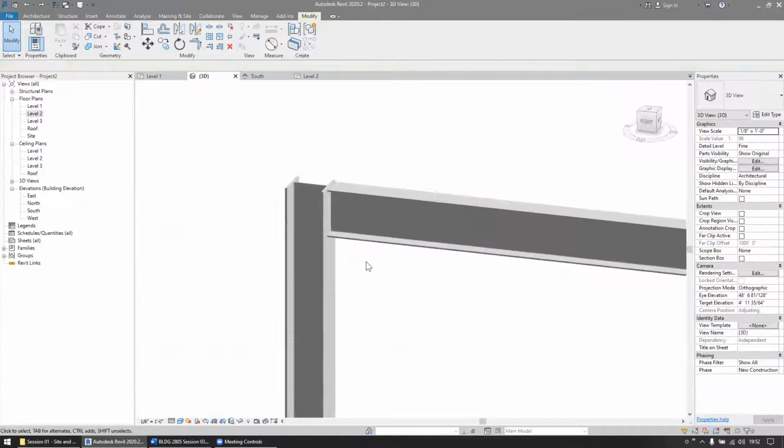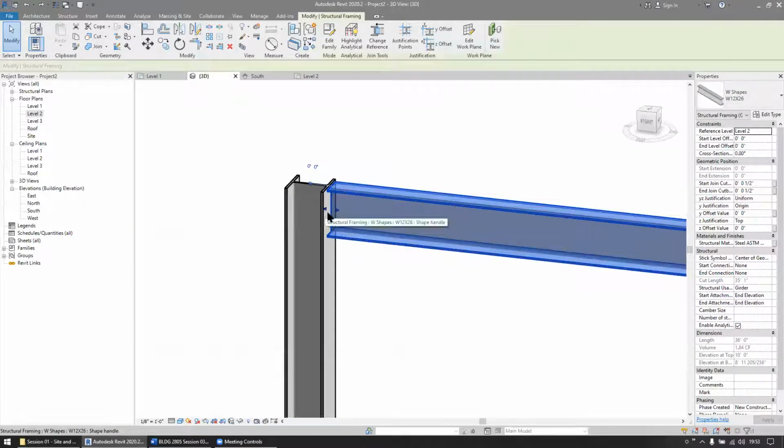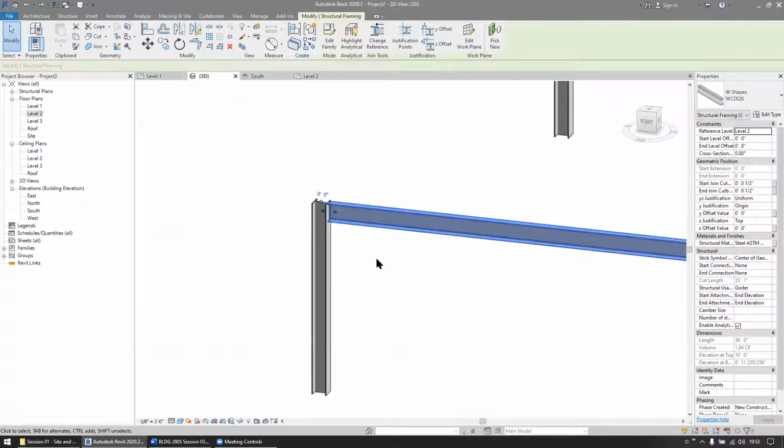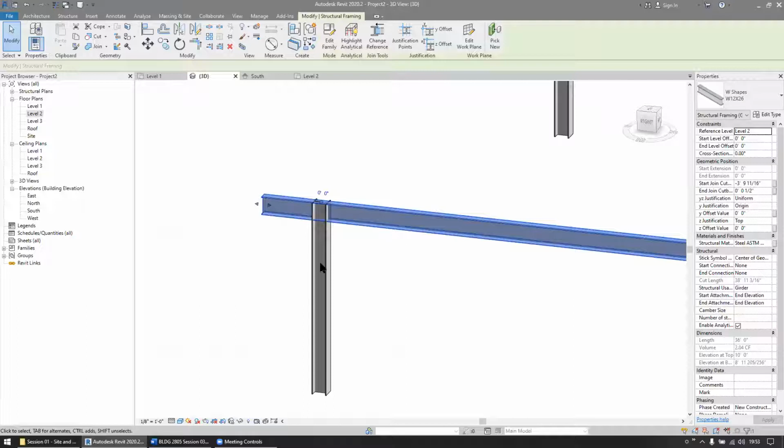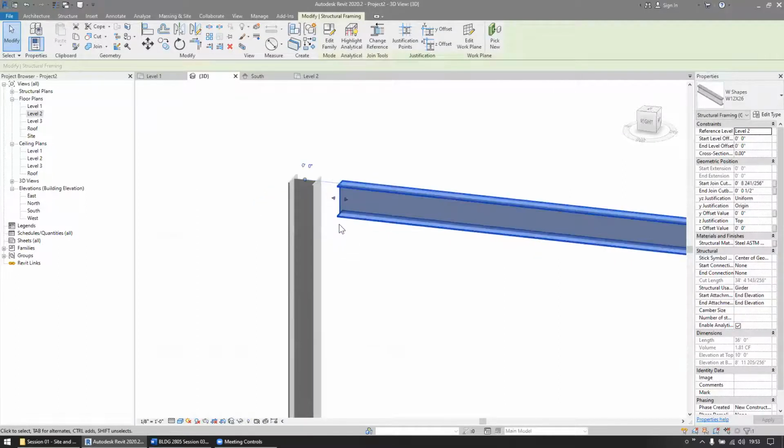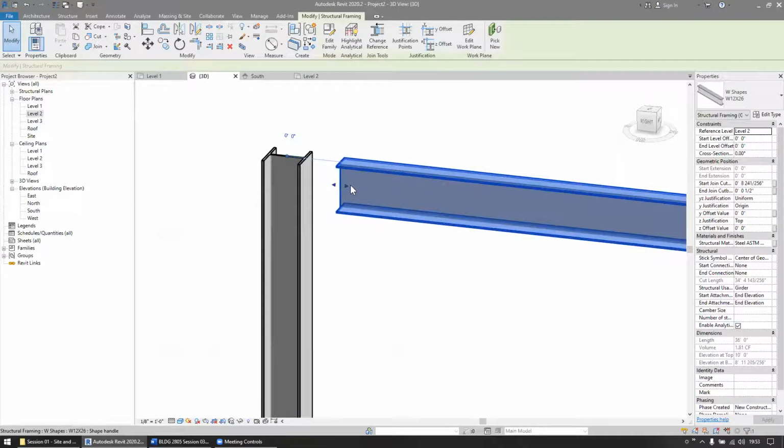So these triangular handles are called the shape handle. In this case, if you want to show a non-structural cantilever of this beam, you can drag this thing out past the other side, and that will allow you to extend this beam. So Revit calls these things cutbacks. Now, sometimes we will have a cutback just so we can get some structural engineering stuff here, like a plate and some bolts. And Revit calls that the structural join cutback.